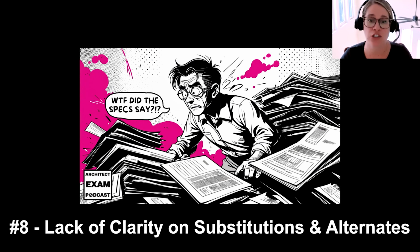A practical tip is to create a standardized substitution request form. These are available through CSI. This form will require contractors to provide detailed information about proposed alternates. This puts the burden on the contractor to actually come up with the criteria that the owner and design team will review in order to approve it, rather than you having to scramble to find all of that information to put in the specification. Using those standardized request forms will help put that work and that research onto the contractor instead.